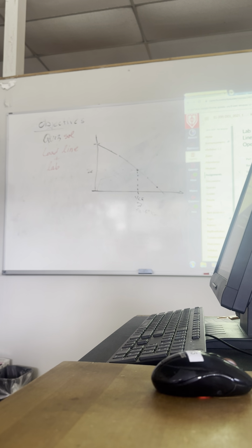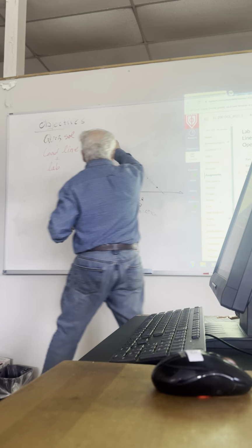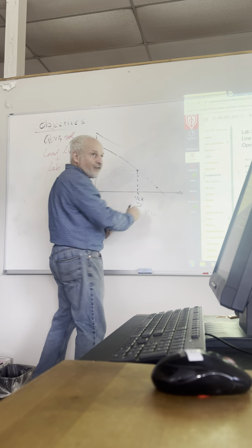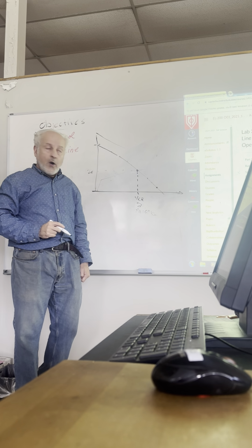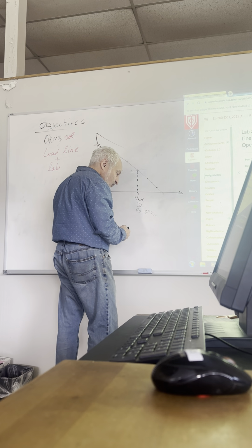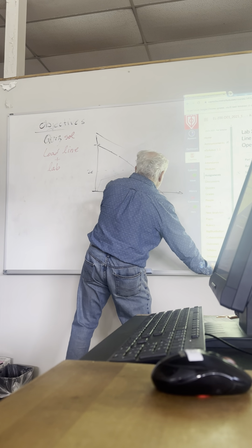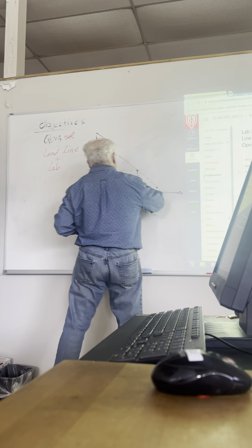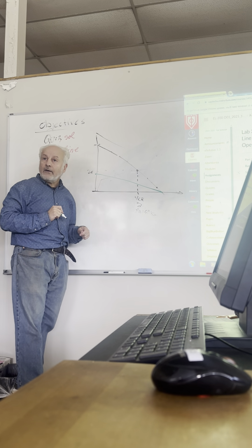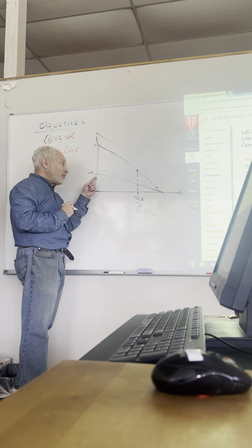So far so good? Yeah, to change the load line, change the RC. If you want to change totally the load line, you change RC. Or VCC and or RC. What if I change VCC and RC? Well, then I can have a load line here. You with me so far? It goes in parallel. What if I just changed RC vis-a-vis where I was? Then you would have something maybe like this as a load line, especially if RC is big. You with me so far?